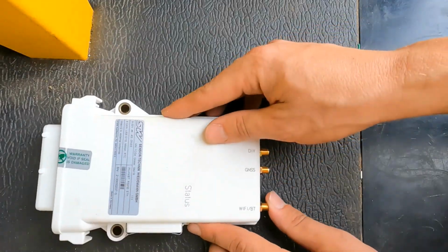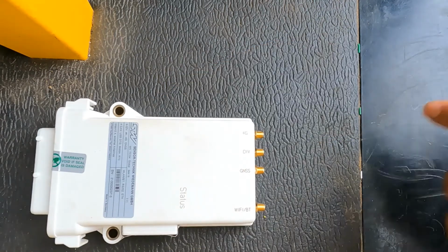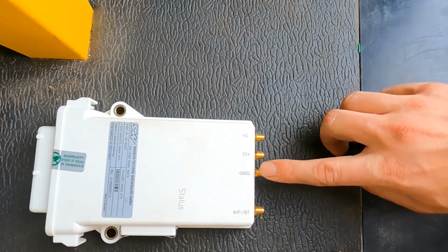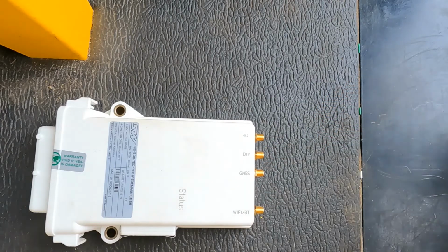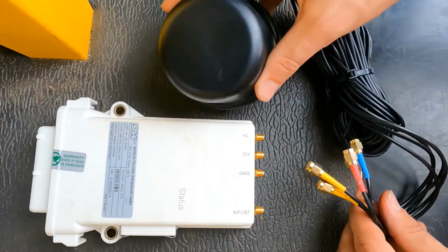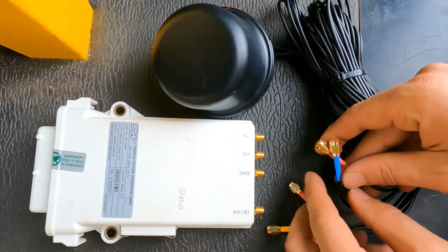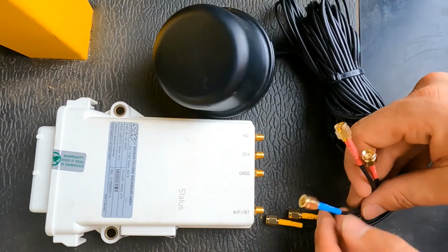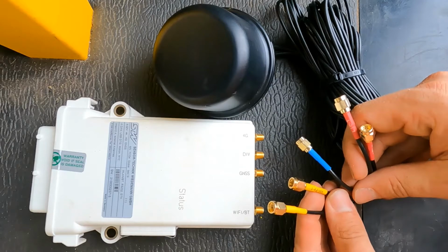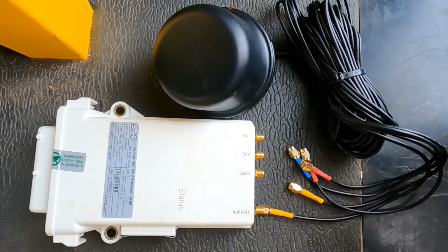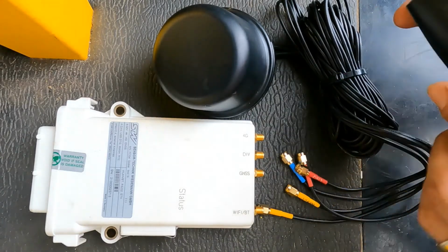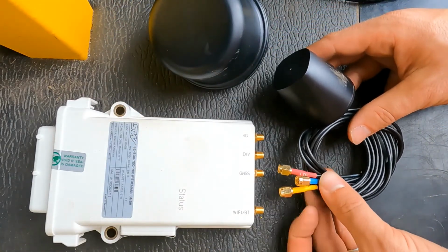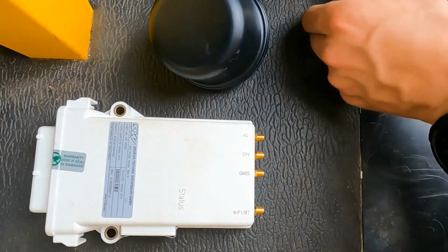Alright, so let's go ahead and start wiring up the antenna. On the side of the TCG4 we have a 4G port, a diversity port, the GNSS or GPS, and the Wi-Fi Bluetooth port. If you order the dual antenna, you're going to notice it'll be 5 wires. The blue one here is GPS. You'll have 2 LTE ports, which are 4G, and 2 yellow Wi-Fi ports. Right now the second Wi-Fi port is not used. If you order the single antenna, you're going to have 3 wires to look at, same color coding, just 1 of each. In this case here, the diversity port would not be used.